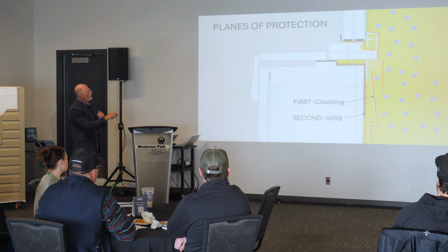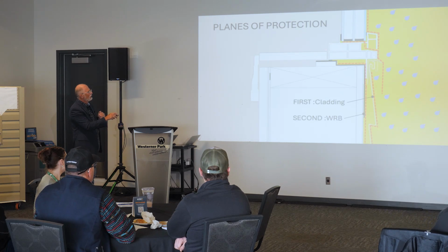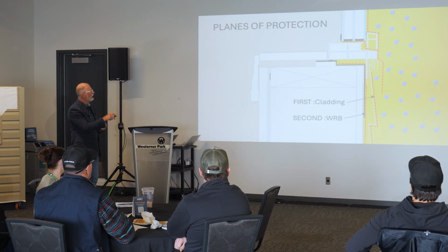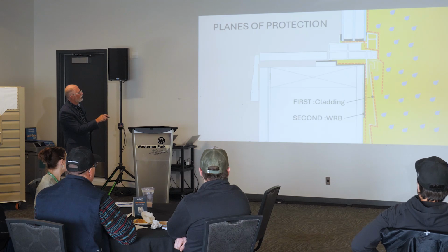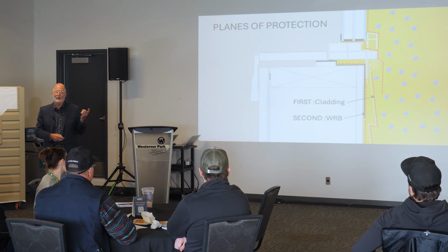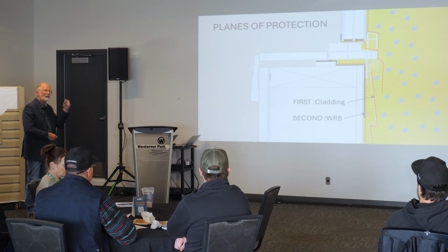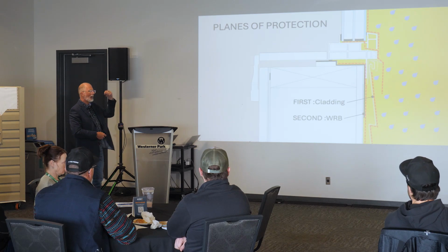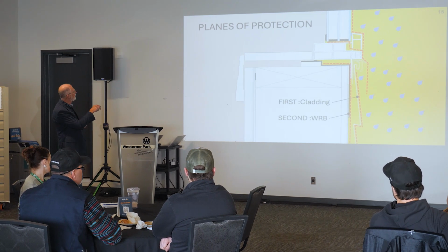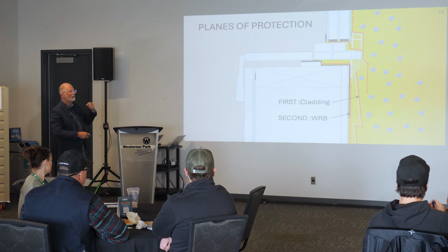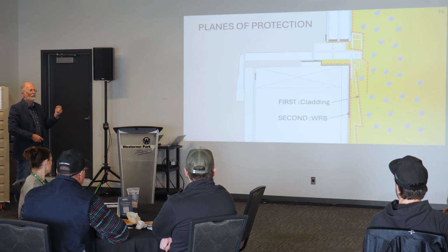What about the risk of condensation up here? There's where we're worried about. And again, if we're worried about condensation internally, what's the R value right here of this particular window? Probably about R2. It's the weakest point in the whole assembly, depending on the type of material you're putting in there. So the risk of condensation is fairly low in that assembly if you look at the building science behind what happens and why you would get condensation. If the house is at 35% humidity, over here it's probably 80, 90% humidity. It's probably still not enough to cause condensation, depending on the temperature.